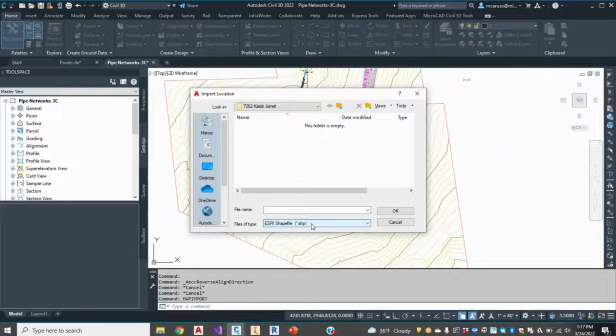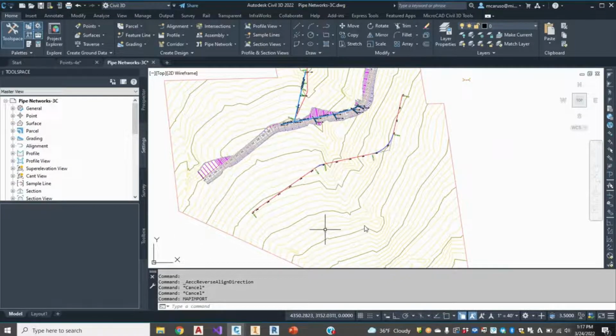And what this does is it will convert a shapefile depending on the type of shape, because there's about 3 or 4 kinds of shapes: points, lines, and polygons. It'll find the equivalent AutoCAD object and convert that into AutoCAD native entities, okay? But the good thing about it is you also have the option to bring in some of that extra data that's attached to those objects. So when the polylines come in, if they represent parcels, for instance, you'll see the parcel properties in your AutoCAD properties window. So that's sort of the old school way, if you will.